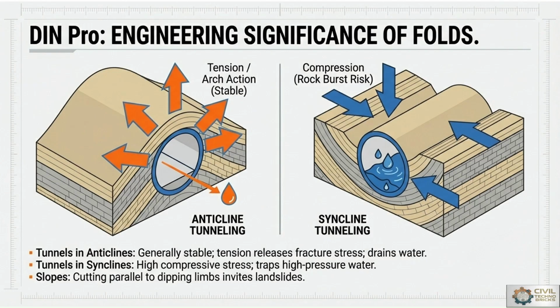The engineering significance of folds, or we can say the applications or importance of folds from a civil engineering point of view. The rock layers or structures are most important from the tunnel construction point of view, where the pre-existing rock layers, their patterns, and their orientations must be studied by the engineers before starting the actual construction activity. So, tunnels in anticlines and tunnels in synclines, as anticlines and synclines are the classification of folds.